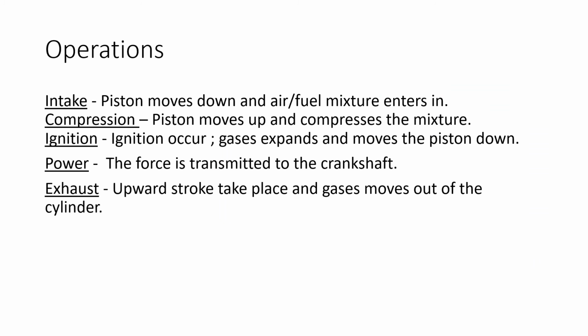Now, what is the operational mechanism of the piston engines? What is the mechanism on which they work? So, step number 1 is intake, from which the air enters in. The piston moves down and the air and fuel mixture enter into the cylinder. And then comes the compression. The piston moves up and compresses the mixture. And then we have igniters that ignite, and the gases expand, and due to this expansion the piston moves down.